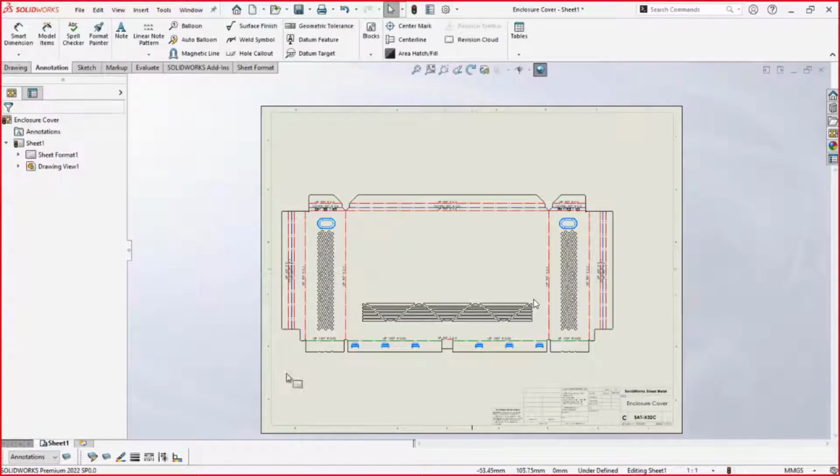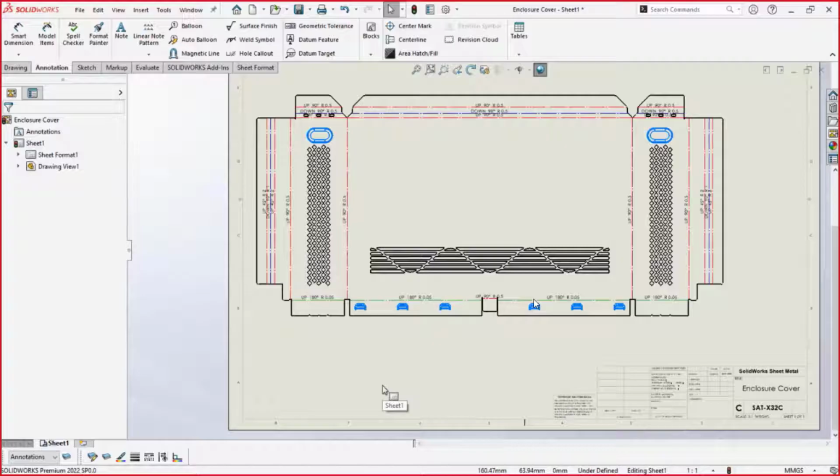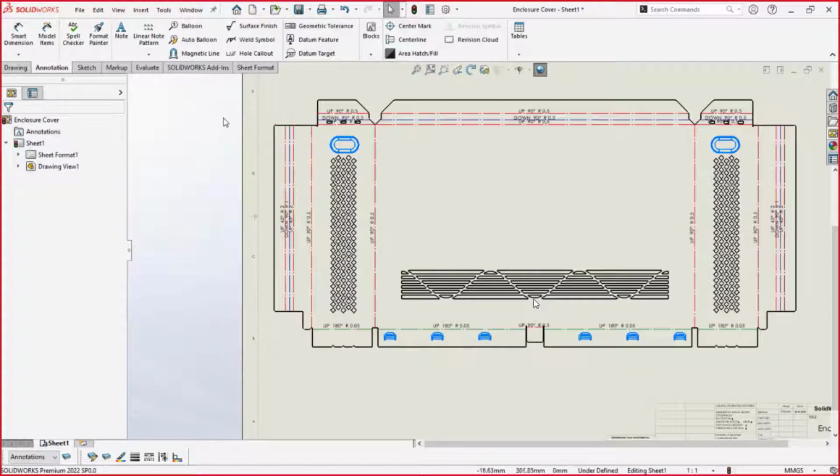Yep, you could see this is the flattened view, which has all the annotations and the bend angles and the bend lines, the bounding box, if you want, you can include. We have the layers and the forming tools already included. If you want to exclude them, you can directly go to the document settings and turn it off. Okay. So if you want to give it for the laser cutting operation, you need to convert this into a DXF format. You can do it by using the save as option. That is also one way. Or else I'll showcase a few more methods.